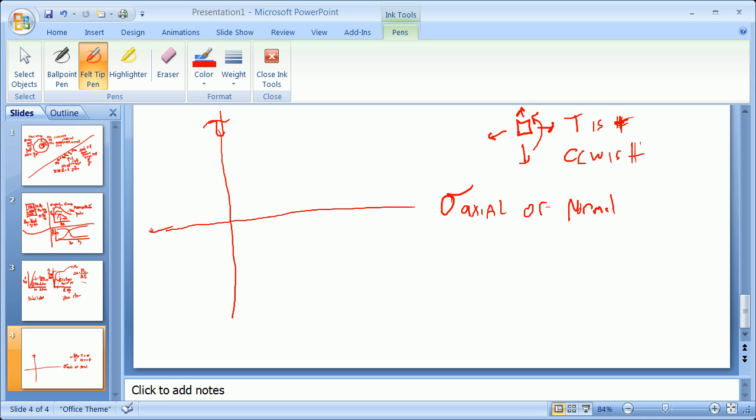And what we end up doing then is realizing that these are also PSI or KSI, and this is also PSI and KSI. And by effectively taking a soil or a piece of concrete and realizing that it is under different stresses, perhaps in this direction and in that direction, we can graph up the stresses on face 1 being the vertical and face 2 being the horizontal. In this case, if there was no shear, we have tension on face 1. We might have a tension someplace like that. And when we have compression, which is negative on the other face, we can then draw a circle, bad as it is, and any point on that circle is going to describe a combination of stresses in the axial or normal and in the shear or basically perpendicular to the normal set of faces.